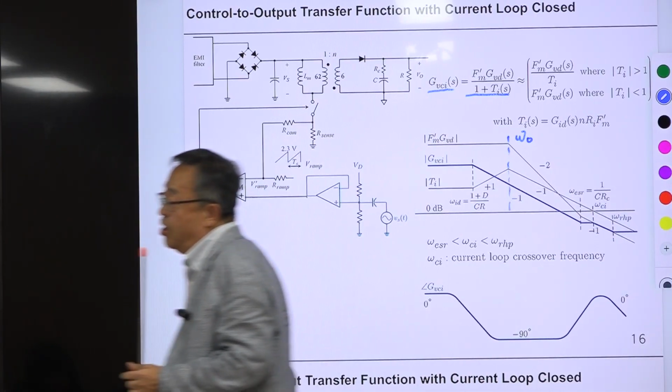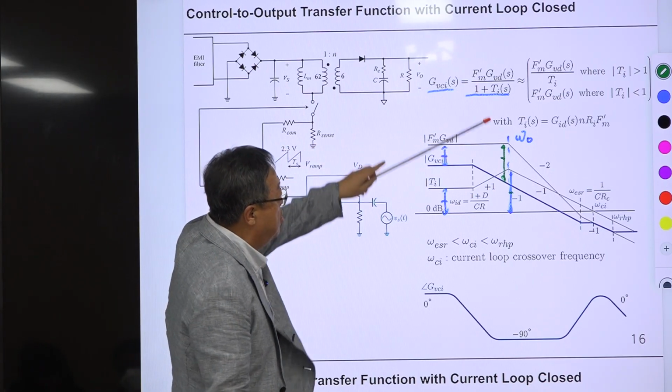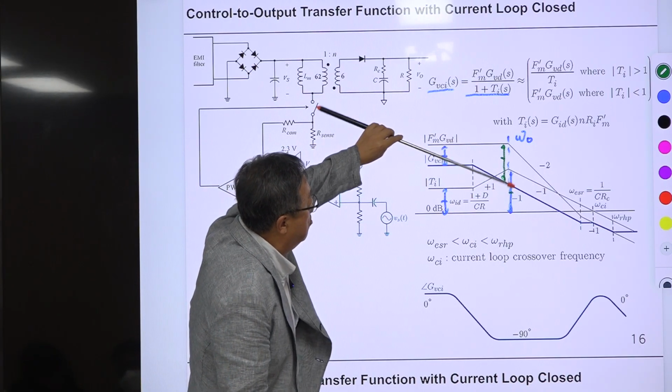Okay. So at low frequencies, this much is subtracted from the upper curve. Okay. And at this point, at the double pole frequency, this much is subtracted from the top curve. So this should be the same. Length should be the same. Okay. And you can calculate the slope here. This is zero slope, and you are subtracting this slope from here.